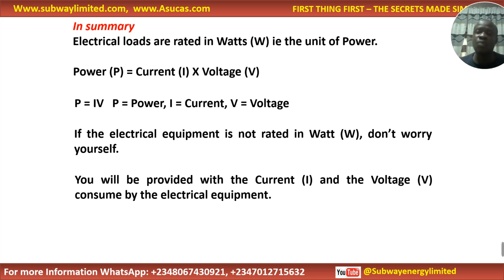So we told you that we want to expose you to the nitty-gritty surrounding the solar industry, the mistakes that people are making in the industry that are contributing to their solar system failures. One of the mistakes, very costly at that, is not conducting a professional power audit, not getting information from the client, because client information will always inform you of how to design the solar system.